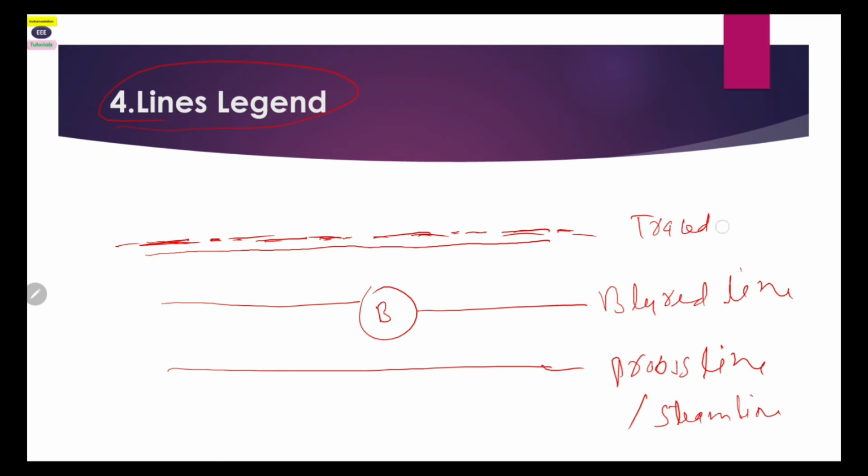because in some areas, if we have to maintain the temperature of the line, then we generally use tracing. It may be steam or electrical tracing. There are generally two types of tracing used in any process: steam tracing or electrical tracing.